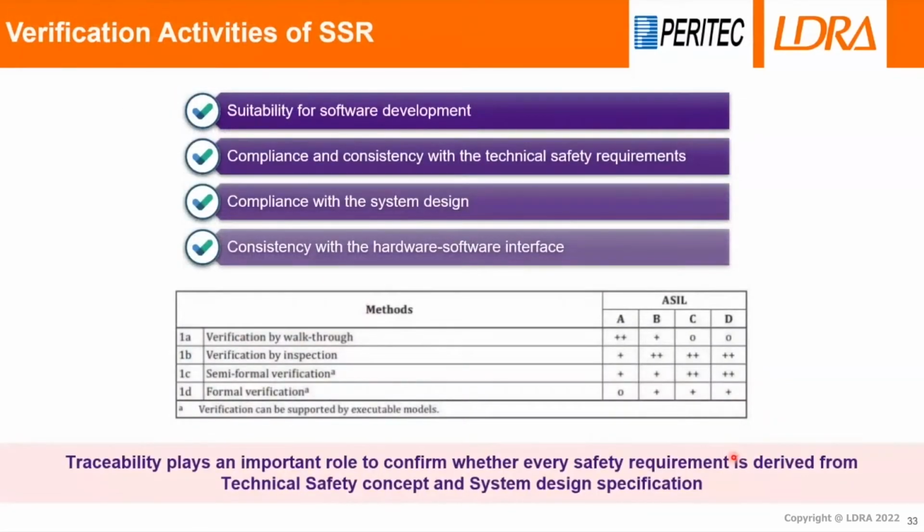And for the verification activity, you can see here that verification activities are defined in a table which talks about walkthroughs for lower SIL level. If it is a highly critical application, you need to do the verification by inspections. And formal verification is just a recommendation. If you have formal tools, you can do it. Otherwise, semi-formal verification can be done by using automated tools.